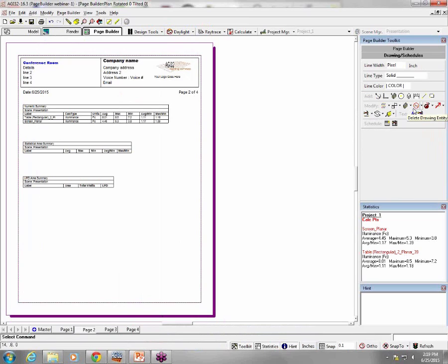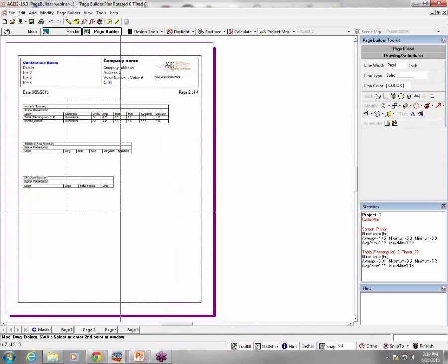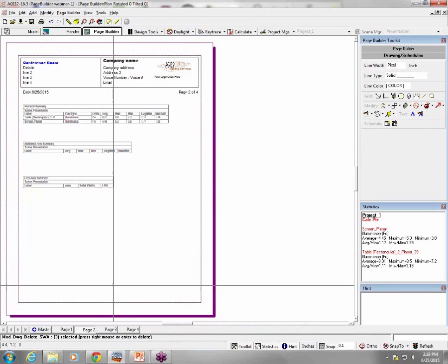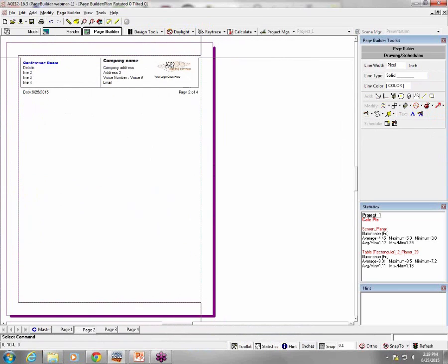So schedules are considered drawing entities, so I'm going to select delete window, draw my window such that it includes at least a piece of each of the schedules that I want to go away. When I click the second corner of the window, those 3 go gray. It says down here 3 selected. Right click and they're gone. A nice clean page now.